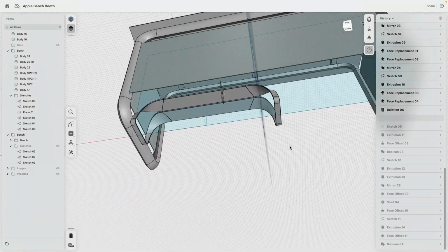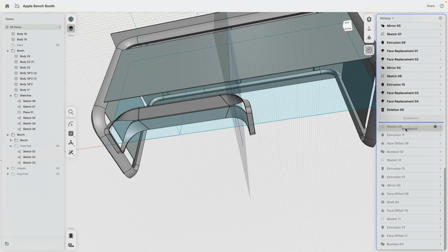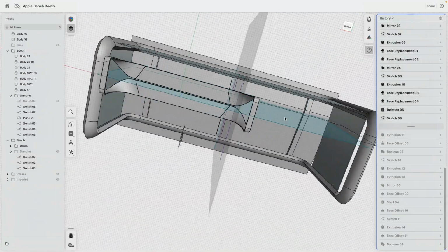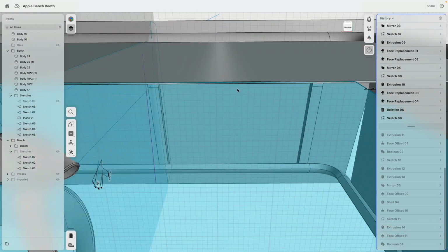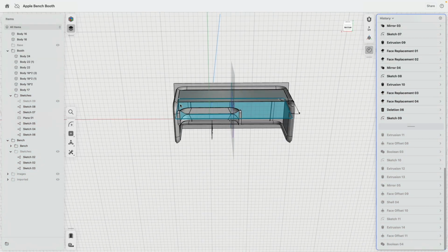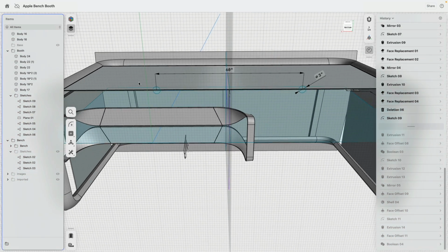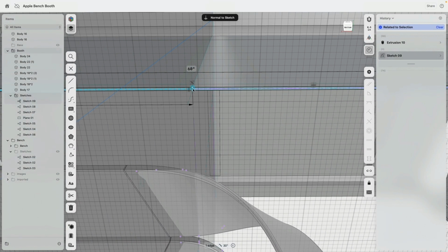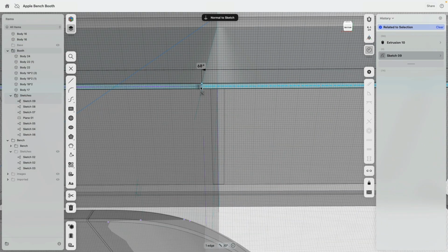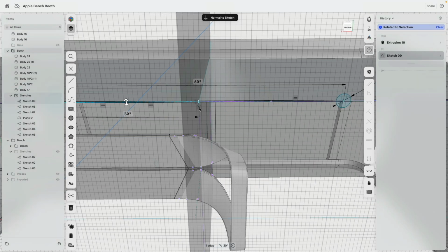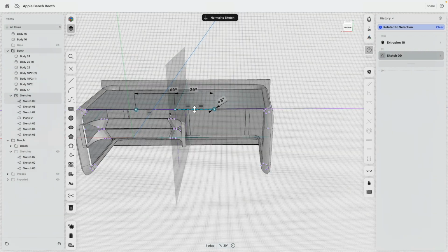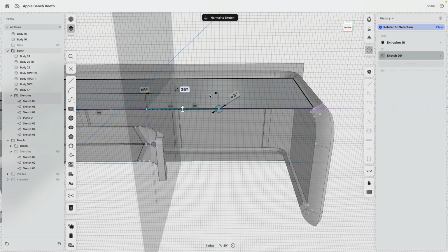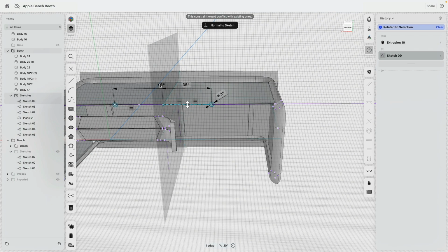The glass actually needs a little bit of support. So on the bottom of this glass, I created a new sketch. There we are. There's one line that goes to a midpoint, another line. I drew a line perpendicular through the glass. These go to the midpoint, everything 90 degrees. These two lines are equal. And this way you can develop a symmetry very easily.